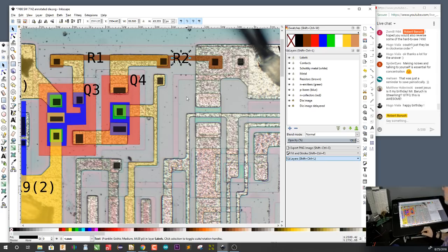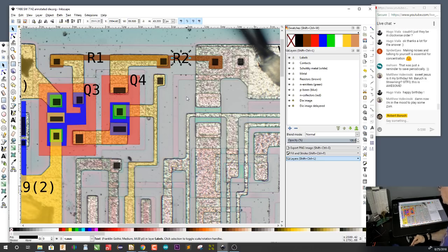We haven't fully reverse engineered the chip, but you can see kind of how we're getting there. We're getting to that point. Typically what you would do at this point is you would hit the books. There are textbooks out there about TTL design, and you would see what a typical standard TTL circuit would look like.